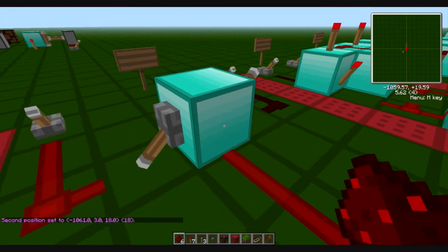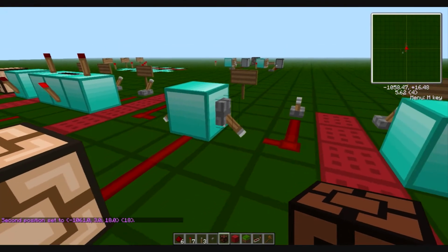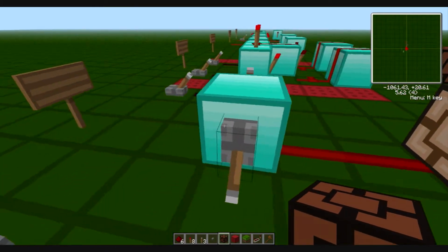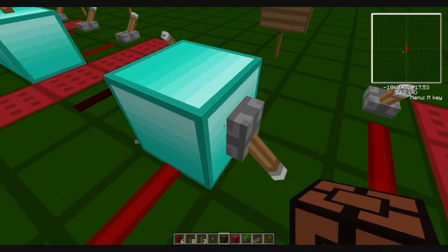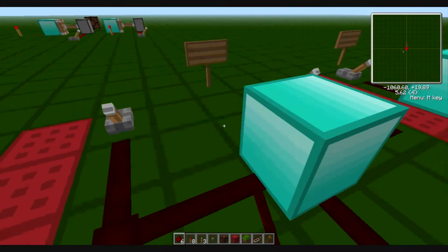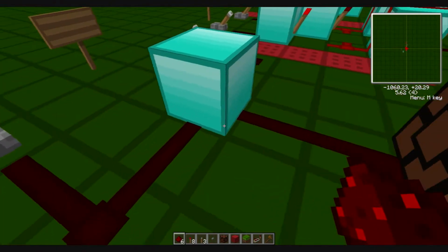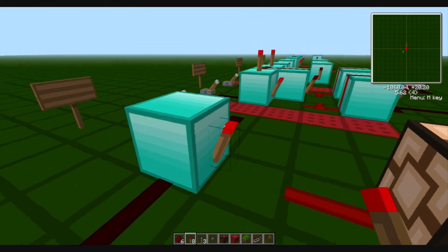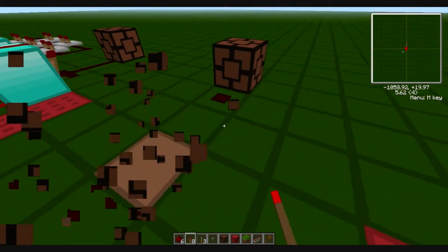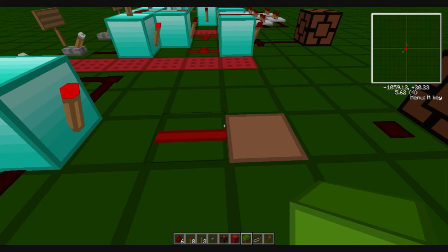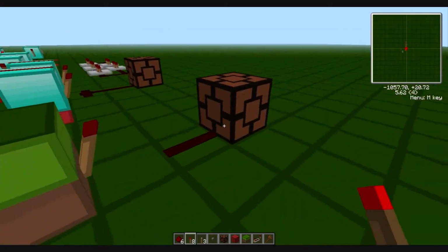And so doing that, you don't need to invert it. You would just leave it, as you can see here. But because I decided to use the switches off the actual block, since they power this block, when turned on, the power doesn't transfer through. But what it does do is it powers this inverter and turns it off. And so I've just taken that and then inverted that symbol or signal to make up for this inverter, and we have our OR gate.